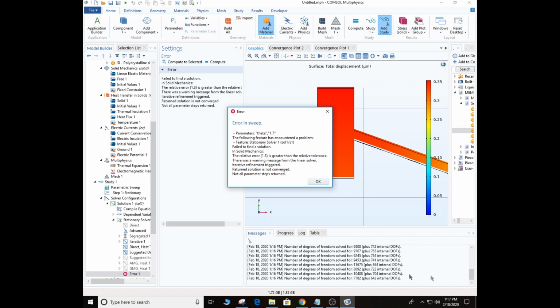That could be. Yeah, that's kind of interesting. I wonder if that's due to my mesh. Maybe it could have been a finer mesh. It didn't surpass my relative error. Well, it said 0.7, so at least we know it's going to.